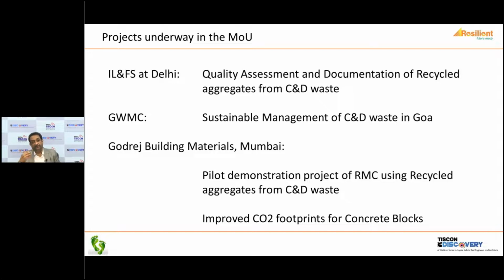block. When you use C&D waste, you have quite a lot of material which is unbound, which has got some mortar, and this is good for increasing the carbonation. When there's no reinforcement, carbonation is good, especially in blocks. So it can help you to arrest carbon dioxide. So there's quite a lot of good things which is happening.